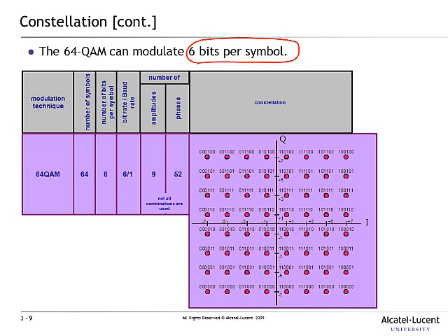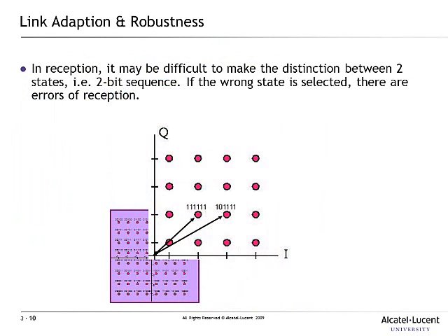This is called adaptive modulation. The modulation technique that is used can change from one millisecond to the next. On a millisecond by millisecond basis, the modulation scheme can change. So there are 3 modulation schemes that are possible in the LTE scenario.